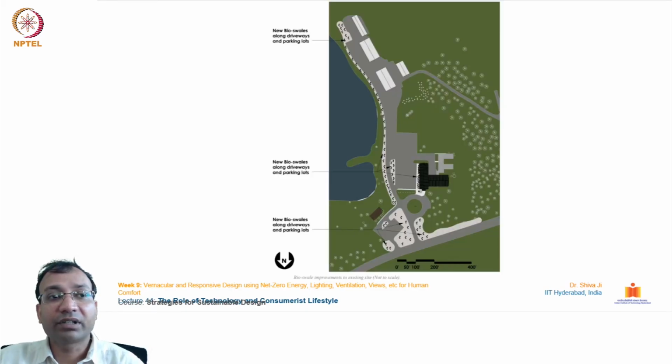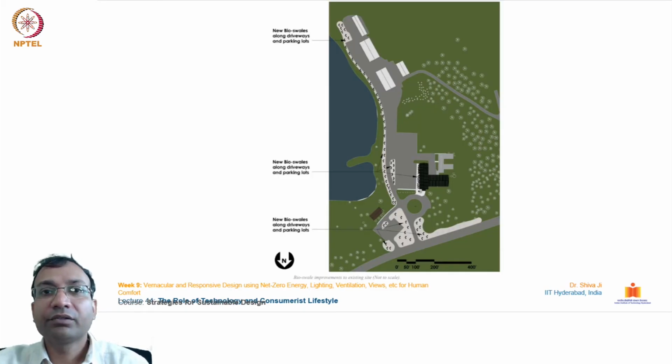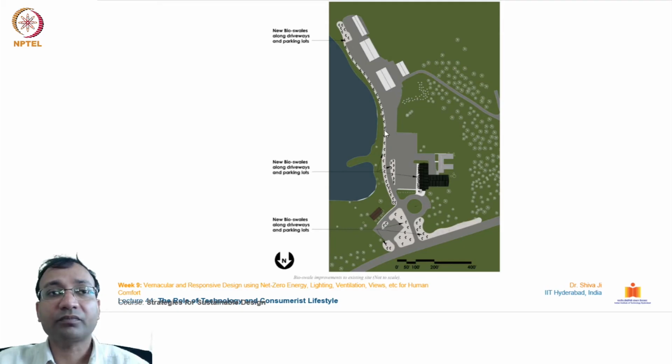Further, I have taken some examples over here for your understanding. So this one talks about the bioswales. Bioswales are man-made linear trenches, which run for longer distances. They can help us increase the recharge of rainwater to the ground. So you see in this illustration how these bioswales are created along this paved movement place, this road, so that all the rainwater which falls on this surface can get accumulated in this bioswale, and this will help in recharging the ground.